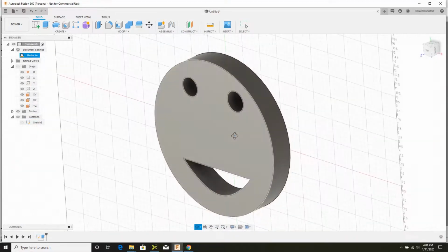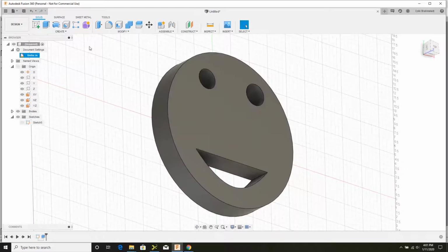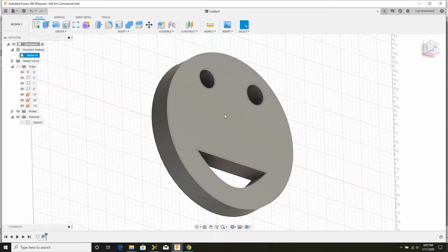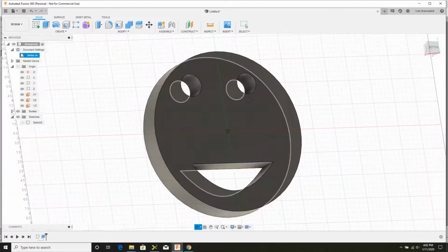That is a 3D thing. You could actually 3D print that right now if you wanted to. You'd hit File, save as an STL, send it to your 3D printer, and you could print that. So CAD is not that hard. So, but great. So we've created a smiley face. That's kind of fun, but not really useful.